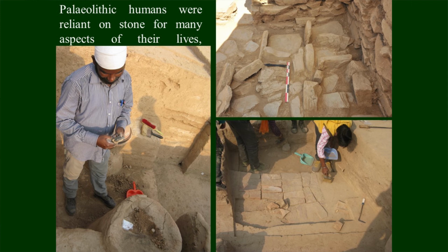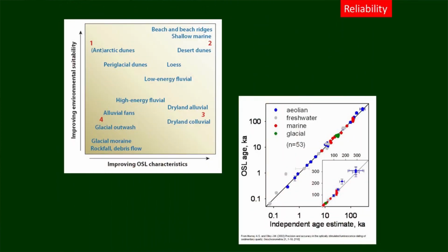I am going to show another example of a terrace. You can see this is a 35-meter section and the bottom 30 meters are totally sand. But on top of this section lies a boulder bed, which is an example of a flood deposit. So the river was flowing at this height and this has been deposited by the flood. So we cannot say that the locations we use for construction in hilly areas, mostly the terraces, are safe for construction, or we should do some engineering work before we construct in these places.